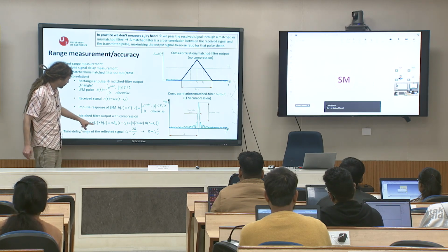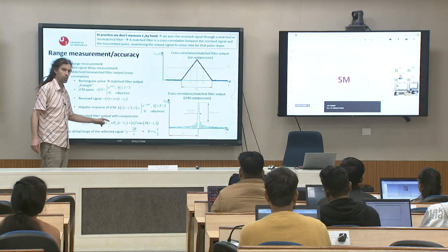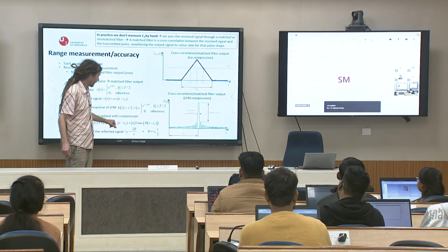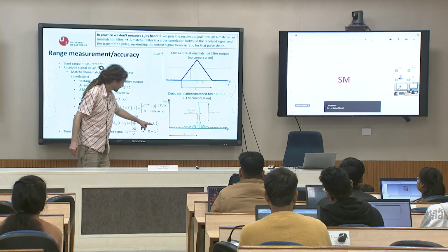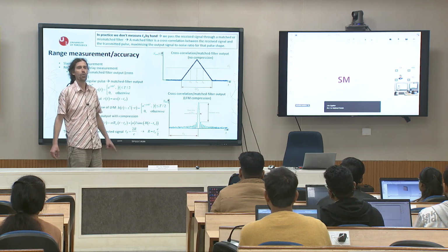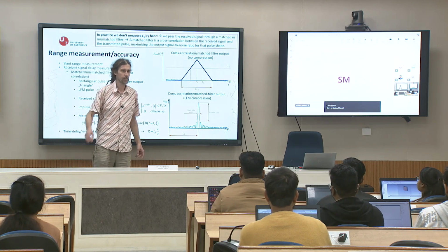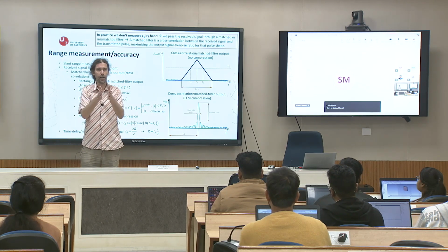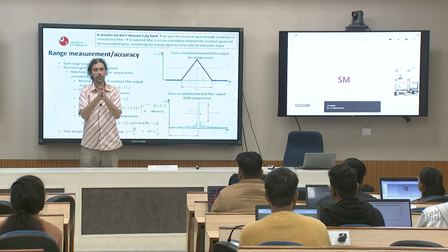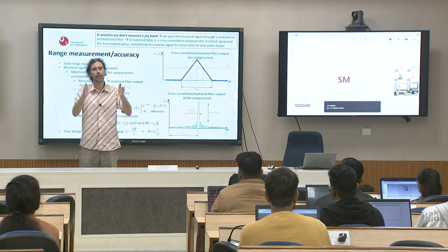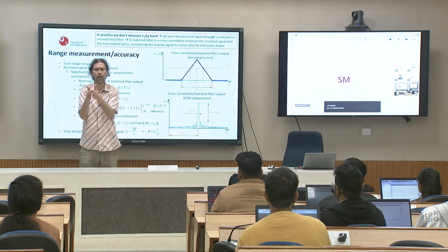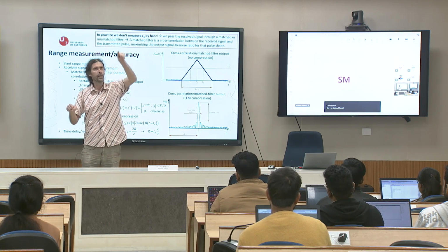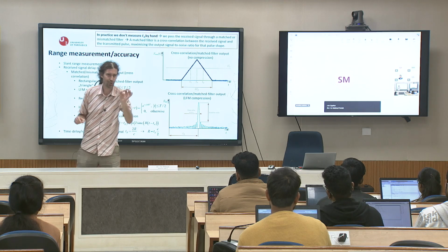So I will compute the received pulse with the impulse response, and you get this function that is a sinc function also. And why? Because if you see the spectrum of the LFM pulse, for enough large bandwidth, not for extremely short bandwidth, it will look like a pulse in the spectrum.